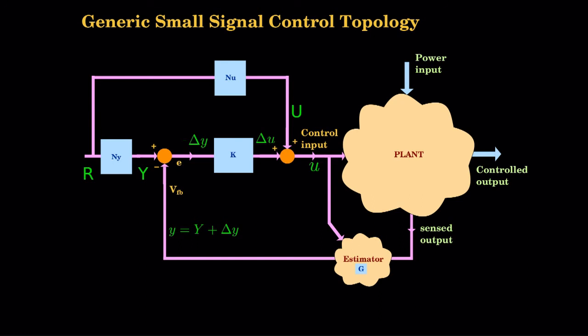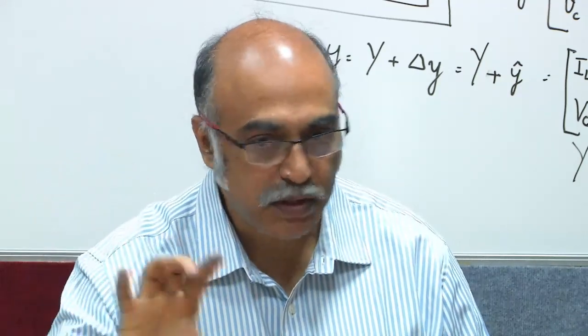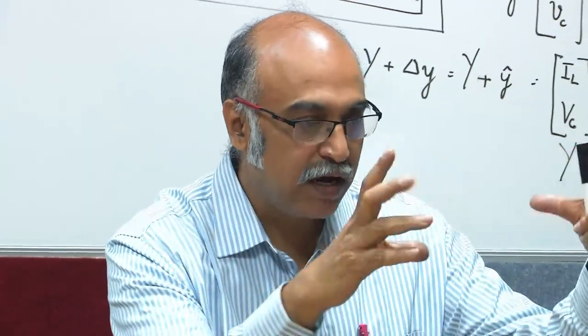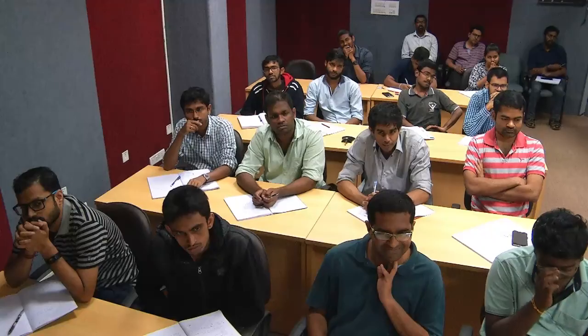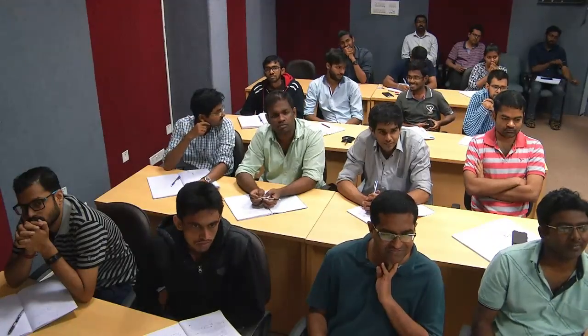It may be a 10th order plant, and you may probably have approximated it to a 4th order plant. So, we will consider that also, and what we do is that we will place the closed loop poles where the closed loop poles of the plant should be, and we will place them within a zone. Never will we say, see, in a typical classical controller design you would have said, the plant has this transfer function, it has a numerator, denominator, zeros, poles, all those numbers are there. So, when you are designing the controller, you have this zero, this pole, cancel, cancel, right? You would do that, no? Have you done that or not? That is the wrongest thing to do.